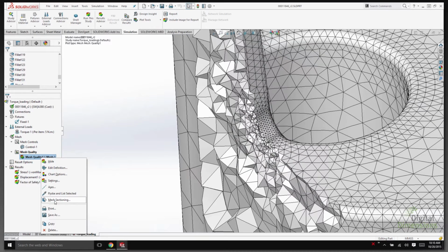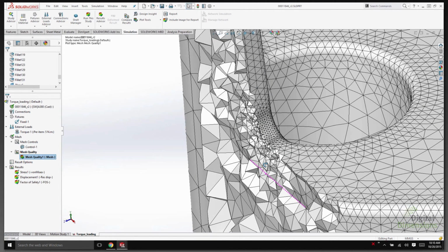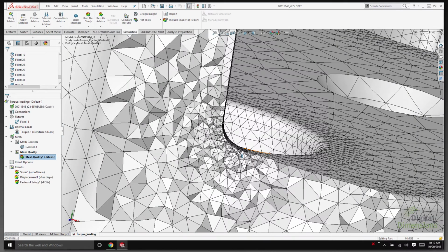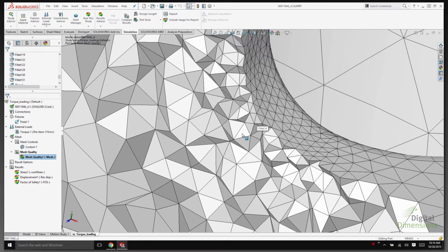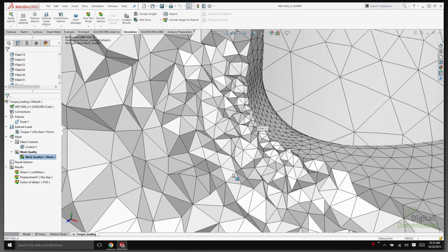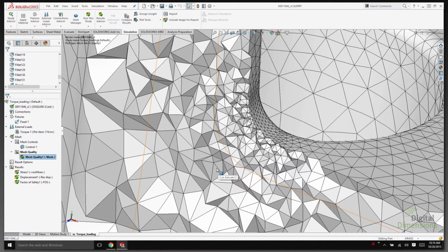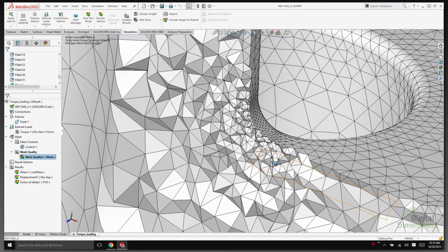Now this mesh sectioning allows me to see the internals of that mesh. So I can actually zoom in and evaluate how the tetrahedrals are actually placed and what they look like as we go through the depth of the model. So we can start to evaluate the stresses and everything that's moving across it. We can do this in more than just the mesh settings preparation. So as we're looking at it now, we're just looking at it from the mesh side of it, right? So some of us might be curious to see this thing in an actual simulation result.